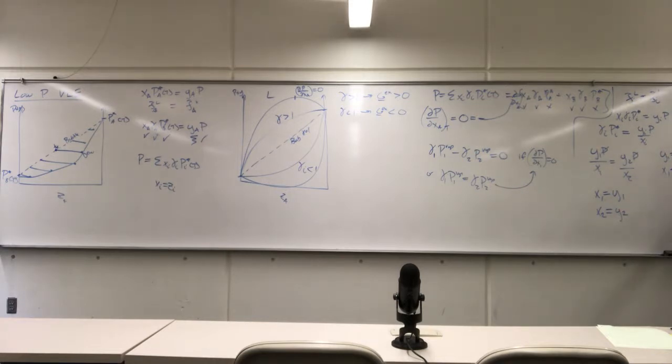So why do we care about azeotropes? They make your separation tough. They make it more than tough. Expensive. Make it impossible. Well, not impossible, you just gotta get creative. You have to break the azeotrope. Without breaking the azeotrope, you cannot separate two components with distillation.